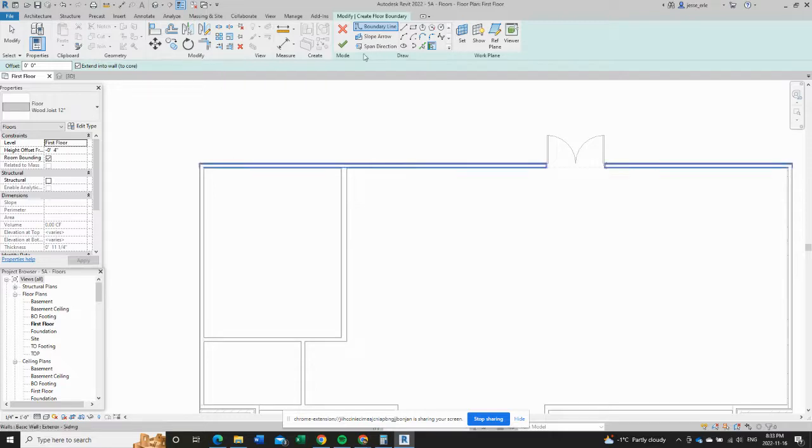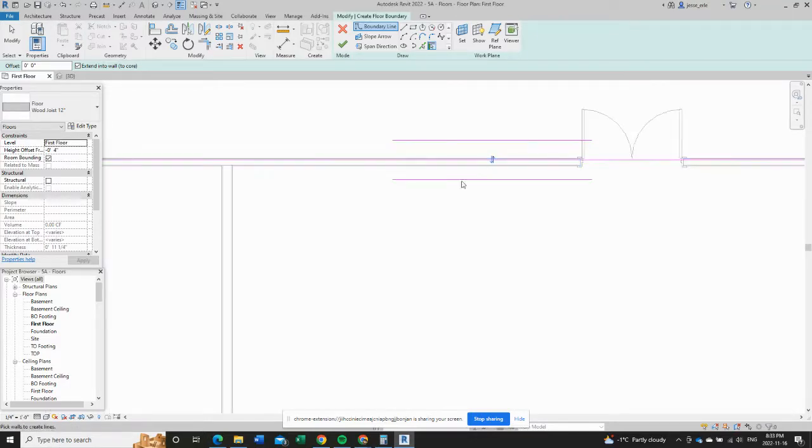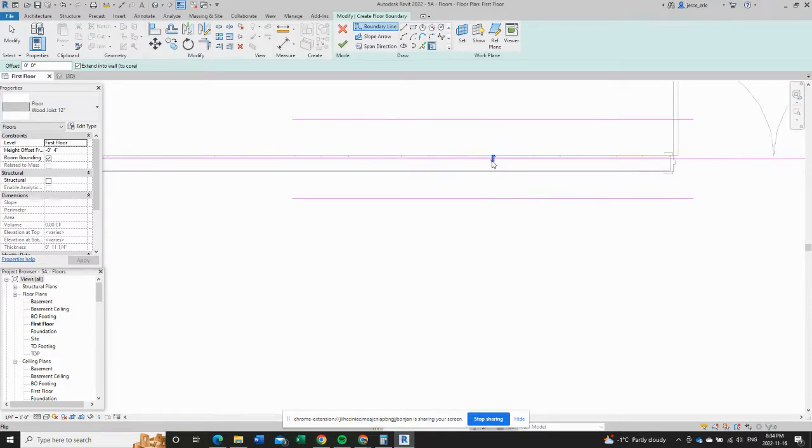Okay. So to get going, we have clicked pick walls, and now we simply have to select walls. We do want to be careful that we are going to the correct point in the wall. And we want our floor to extend to be underneath the framing. If I just move my cursor away, you can see that purple line. That's the edge of the floor. And this piece where my cursor is hovering is the framing. So we can see by the position of that purple line that it is underneath the wall, and that's what we want.